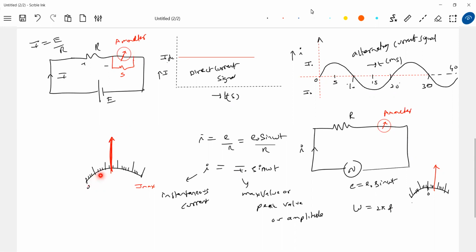Any reason for that? Because you're not permitting the pointer to deflect on either side of the 0, but the galvanometer is forcibly made to deflect. So due to the strain produced in the wire or in that particular galvanometer spring, what we discussed earlier, phosphor bronze, the spring will lose elasticity. After-effects will come, and gradually the displacement will not be proportional to theta. And the galvanometer will get damaged.